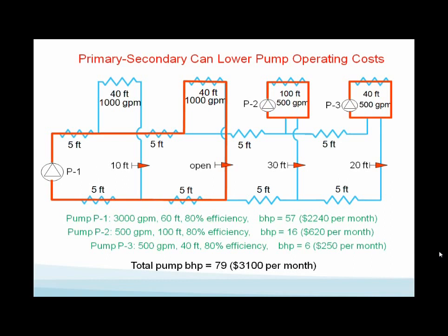You're beginning to see why ASHRAE wants you to take the time to look at systems and pumping and pump head loss calculations. This is a huge amount of savings just by taking the time to analyze the circuits, do detailed pump head loss calculations, and understand where the head is. This is a must. You're going to be in this business, you're going to have to begin to look at your systems. Detailed pump head loss calculation by ASHRAE, by code, and it's the right thing to do.